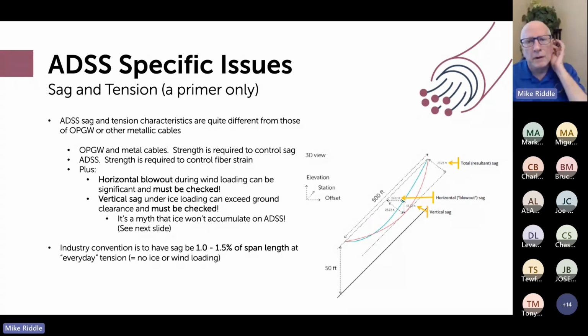So it's more of a balancing act. You can see this if you go to our website. We have this system that helps you pick cables. There's one for OPGW and one for ADSS. If you play around with it, you can get an idea about how these variables interact with each other and lead you to a cable design. And other than that, if you've got a specific case that you're considering, drop us an email and we'll come back with a cable design. And then the strength would be the strength at that point. It would have been designed for that.